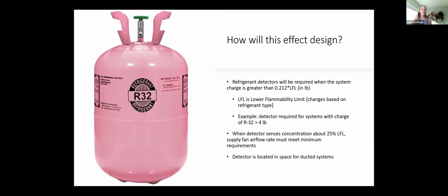Those systems are allowed to be serviced with the refrigerants that they have, as long as their manufacturer or service technician has that refrigerant available. Manufacturers are not allowed to stockpile the HFCs like in previous versions of refrigerant changes. So those refrigerants will be retired relatively quickly.